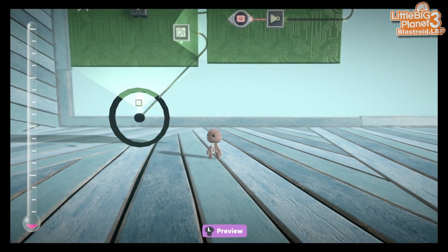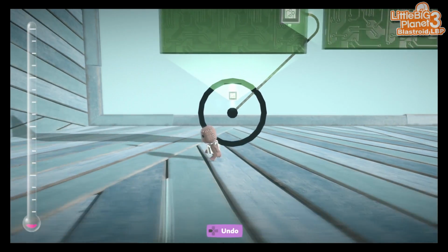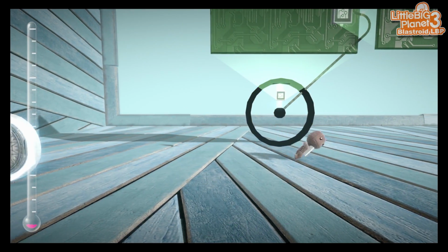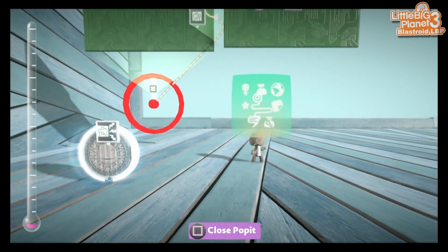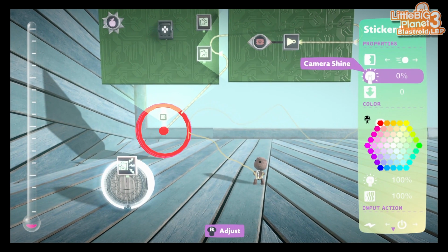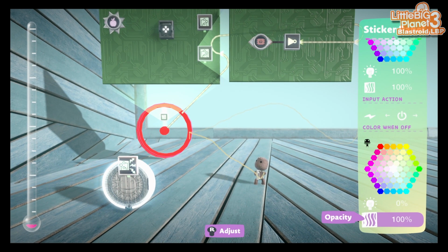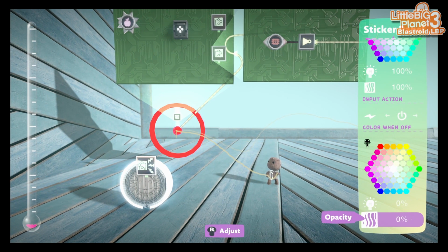We can try this out. So I'm not moving and I can see the thing just fine. As soon as I move, it goes black. Moving the cursor, moving my character, it goes black. Now the reason it goes black is we forgot to set one material thing. So we'll go down here, and when the material is off, we want opacity to be 0. Same thing with this little center area, 0.